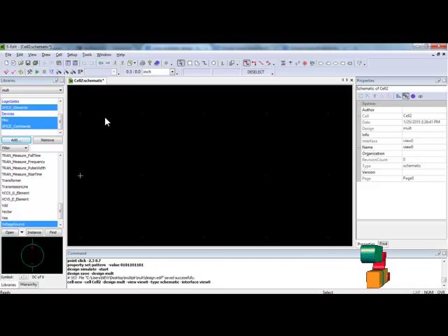Each cell should contain a different CMOS design. The next process is to set up the simulation. Pressing this icon leads you to the simulation setup, where you set the maximum time duration for the design, in nanoseconds.